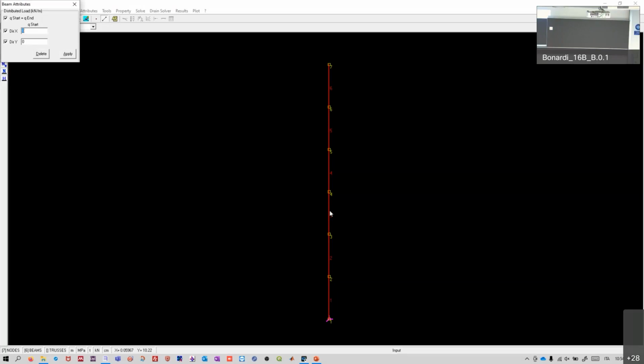So typically what we do is we apply the load along the vertical dimension of the structure. With Professor Gentile, you have seen that if we put some accelerometers at different levels of the structure, what we record in case of a seismic event is some acceleration which increases more or less linearly with increasing height.